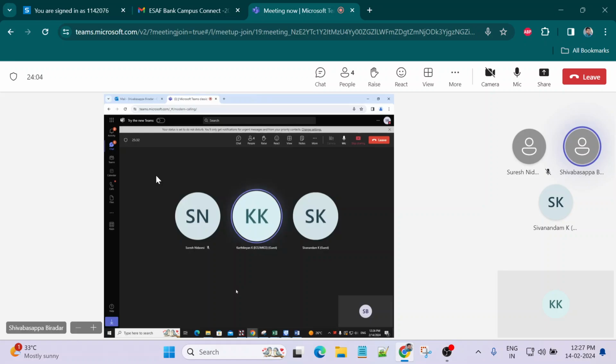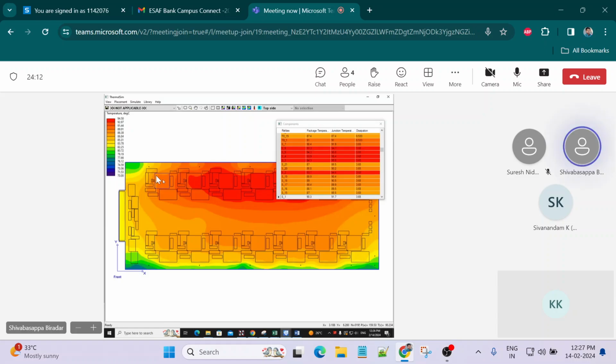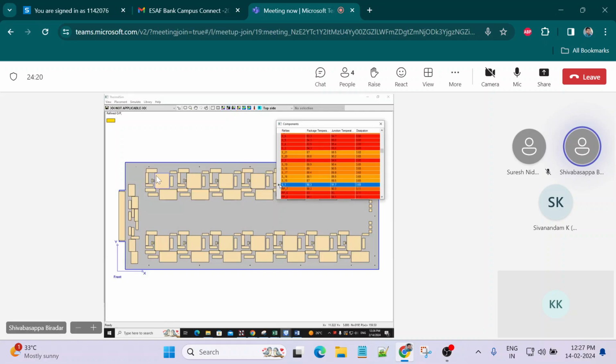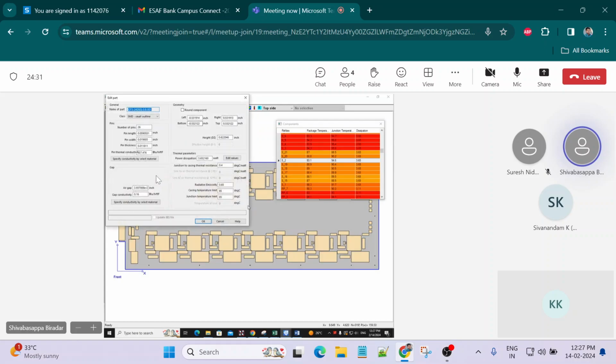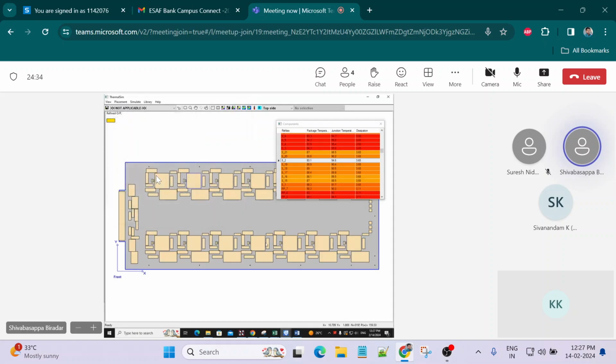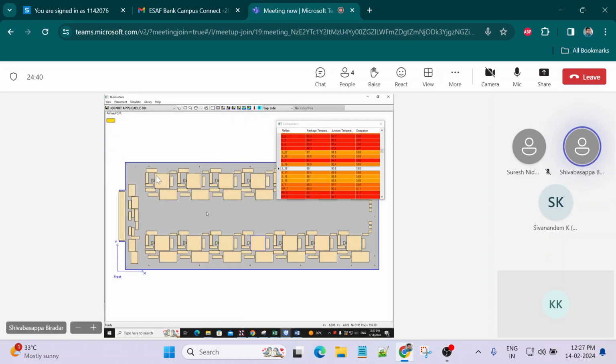Actually, how to add multiple active components in that window? You showed I think one component. For example, after running, this bar will come. Just double click on this. See here it will highlight. Take this one, embed all the things. Then take this, double click on the second component, edit part, embed all. Similarly, for this one, double click on this, embed all. Like this, we have to select whatever active components we have.